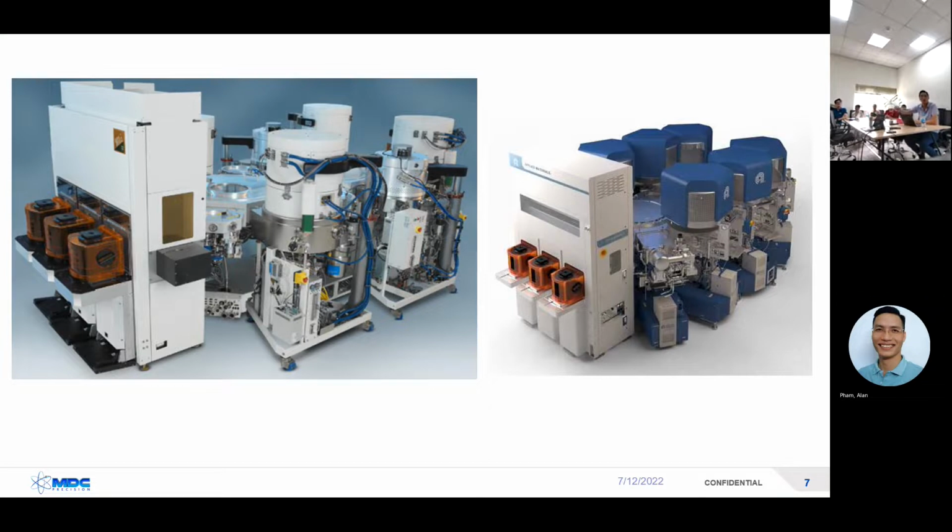Where is this one? We need the, this one would either be under here somewhere or up here. So this is an argon, so this is not a critical process gas. That's probably why this is a looser term. It would probably be somewhere under the middle here because you'd have argon coming in and sending it out to the gas boxes. Like look at this, there's 1, 2, 3, 4. So this is probably, AMAT has, there might be a chamber over here. This is probably a 5-chamber system.